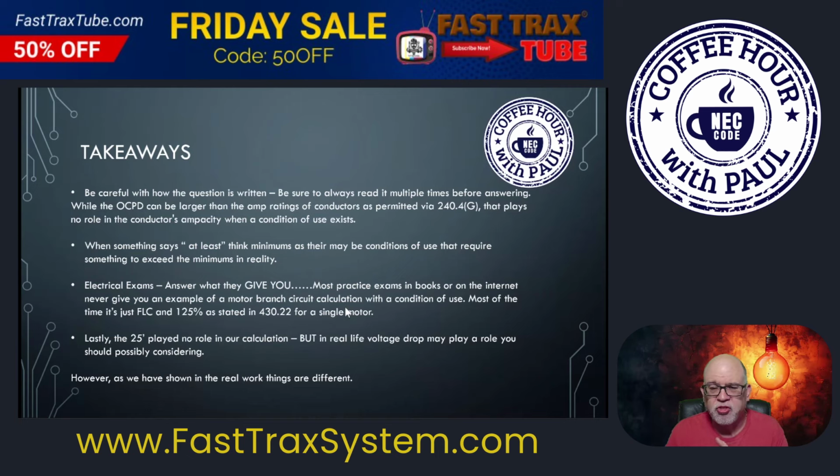Also, remember, in our equation, voltage drop did not play a role. People want voltage drop to play a role in motors all the time, but remember motors have overloads, so even if it was a condition, it's not going to overload the conductors. Should you take voltage drop into consideration? That's a very prudent thing to do, but it played no role in this exam question.